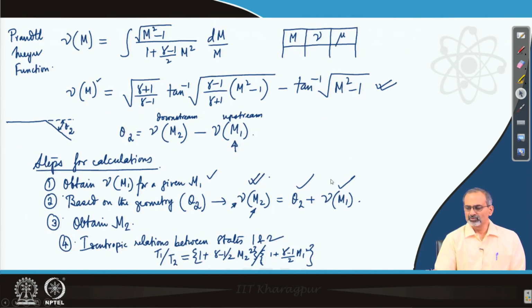And now coming to the Prandtl-Meyer function that we were talking about a few minutes back. So, here is this function nu, which is of course dependent on M, and it is basically this integral that we have shown over here. If you were to integrate it, you will come up with this result, which again is a function of gamma and M, and in the gas tables you can look up tables of Prandtl-Meyer function which are very easy to